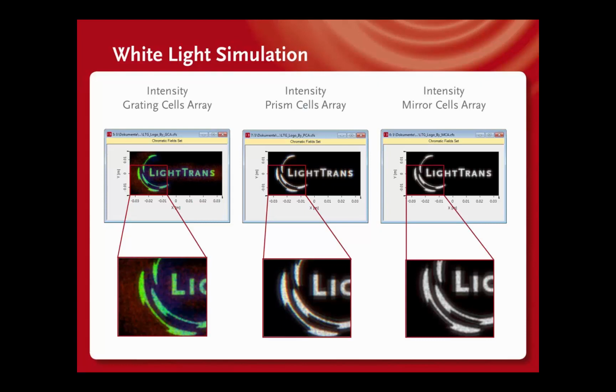That means you should use at least, let's say, Gaussian power spectrums. Most of the monochromatic LEDs have a more or less Gaussian power spectrum, and you should use the correct bandwidth for the simulation, but it is actually better to import a power spectrum.